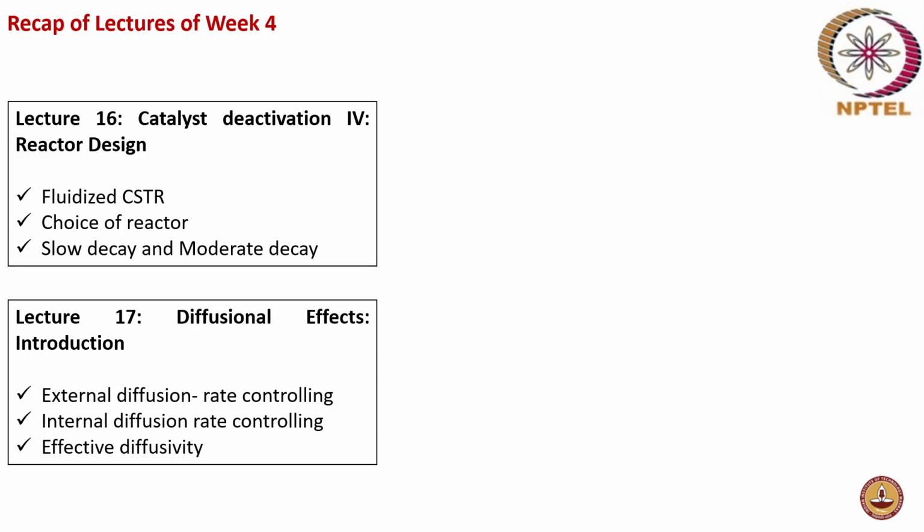So we have to bring in these kinds of resistances that come into the diffusion of the material. That is why the concept of effective diffusivity is introduced, where these restrictions, for example the pore diameter and the ratio between the voids and the solid area, are all brought into the picture. That is why we have the concept of effective diffusivity in diffusion controlling reactions.